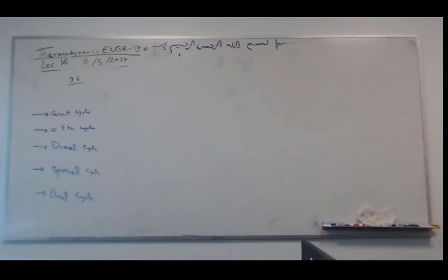Go back to the chart. Even in the PV diagram is better. The PV diagram is better to see V4 equals V1 because it's vertical. In a PV diagram, vertical means constant volume. In a TS diagram, it's a little bit hard. That's why we write on a slanted curve, V equal constant, P equal constant. So you need to know that.